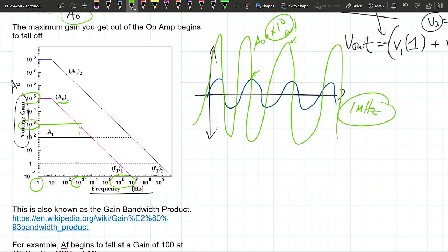And most of the time it doesn't matter, because a lot of the amplifiers you're building, you're going to make a gain of 10. A gain of 100 typically is probably as high as you want to do on an amplifier. If you want a gain of 1,000, what you want to do is a gain of 30, then another gain of 33 or something like that. That way you do this multi-stage gain as opposed to trying to get a factor of 1,000 amplification right out of the box. And so this is a complicated thing to quantify.